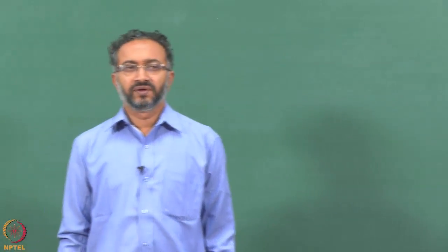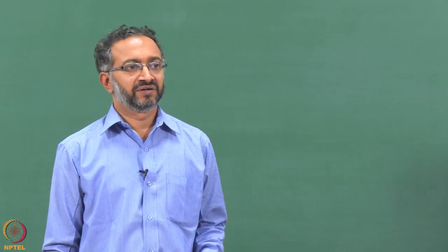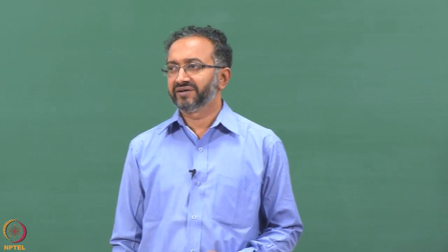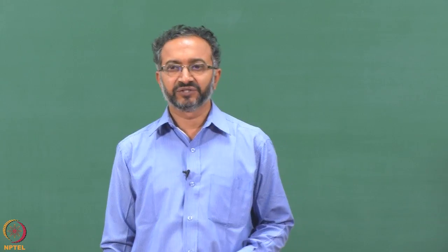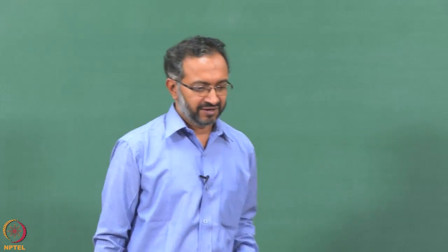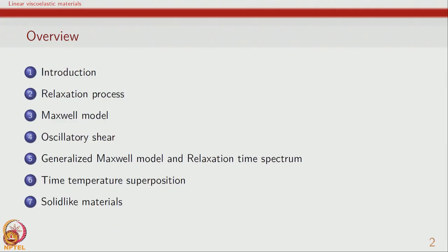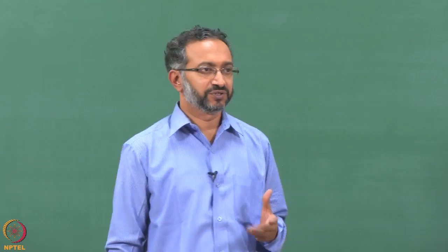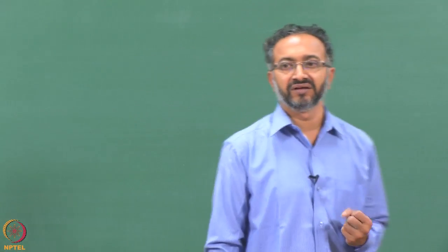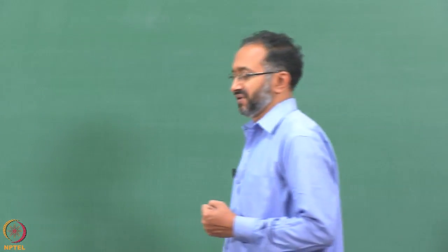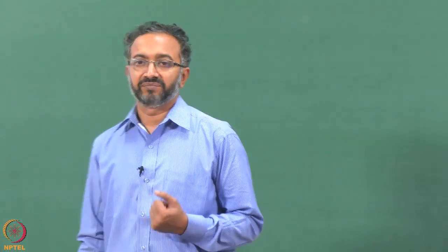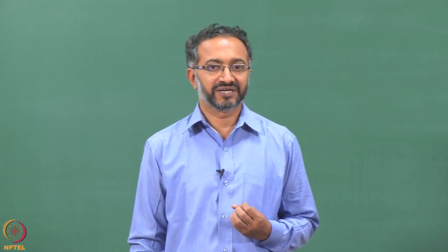So, what we have been doing over the last few lectures is discussion related to linear viscoelastic materials, and so far we have looked at the idea of relaxation process as central to defining viscoelasticity, and the fact that we use Maxwell model as a very simple model to learn about some of the basic characteristics of viscoelastic materials.